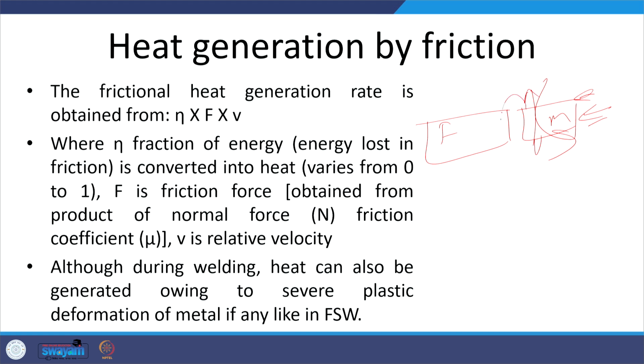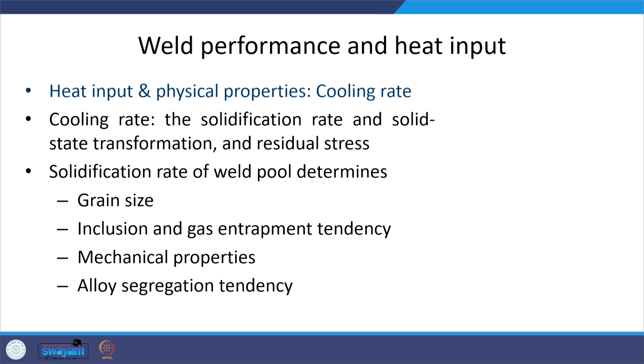some kind of interfacial plastic deformation is also involved. So, not just the frictional heat is generated, but the heat due to plastic deformation is also generated, depending upon the relative velocity, normal force, etc. So that also contributes to generating the heat.